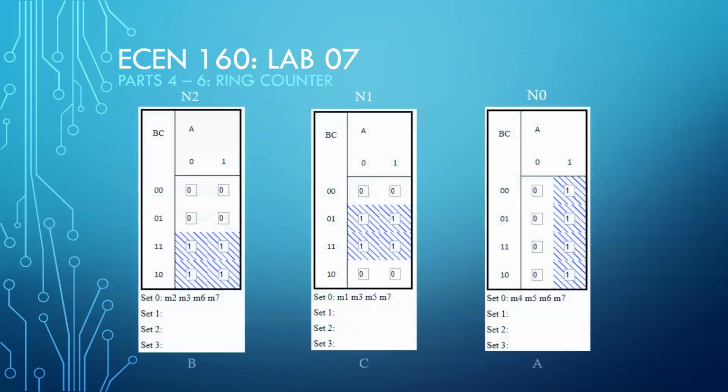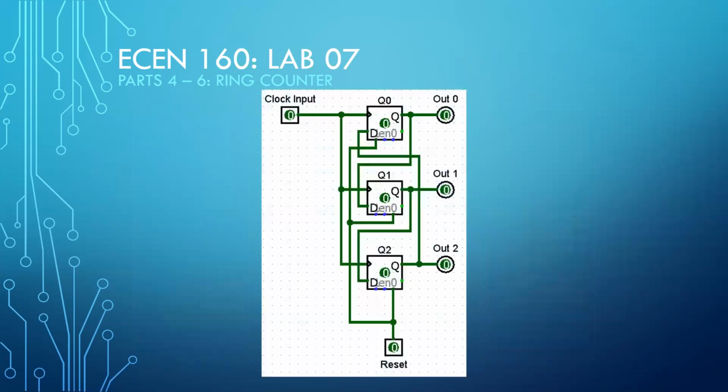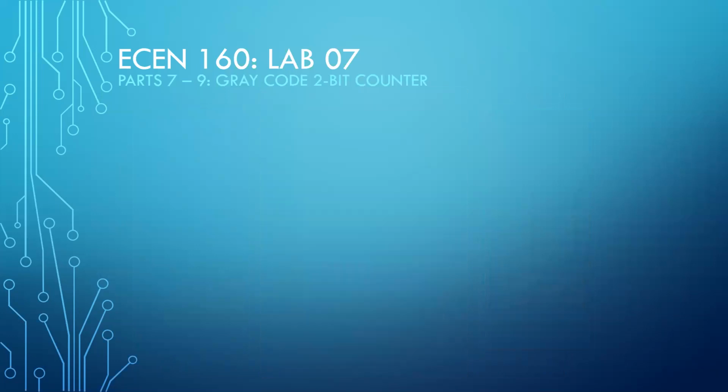This required paying more attention to the transition table to formulate how to order each step in the circuit, but otherwise it was fairly straightforward. As you can see in the circuit, no additional gates were required aside from the D flip-flops.